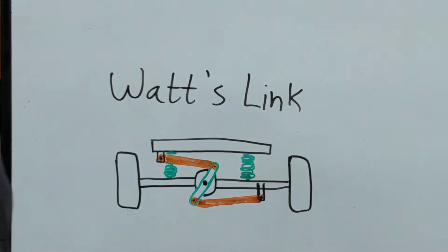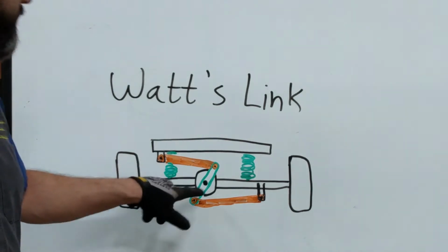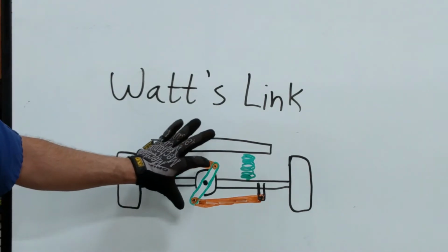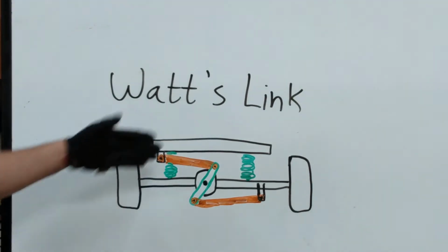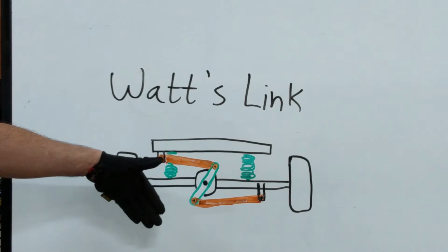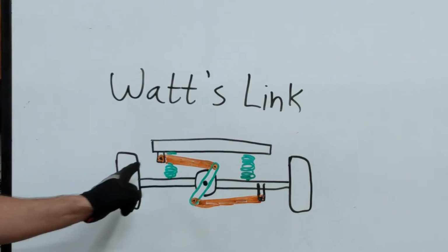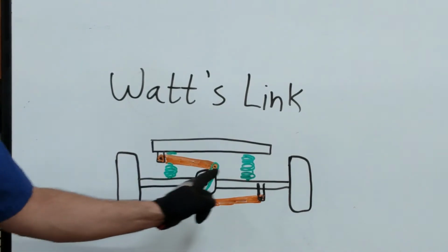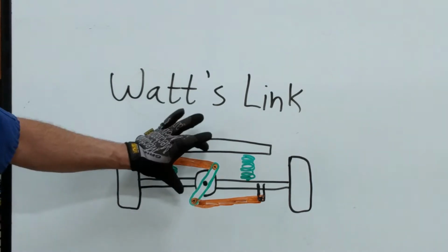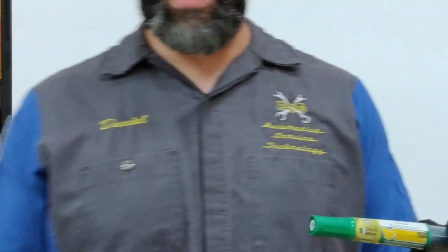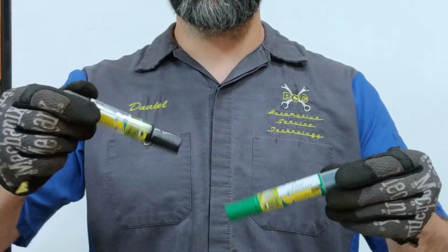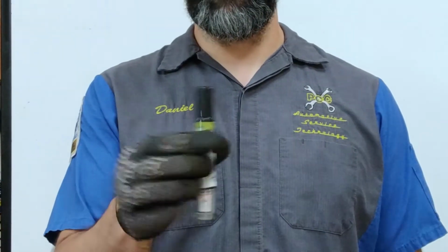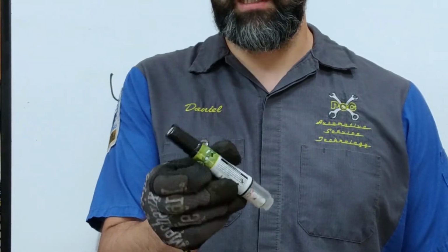But that radial movement, that angular movement, is going to be equalized by this link. So as this arm pivots downward and tries to move farther away from its mounting point, this link is going to pivot. It's going to allow those links to move on their respective arcs and have a piece in the middle that pivots with the suspension movement.